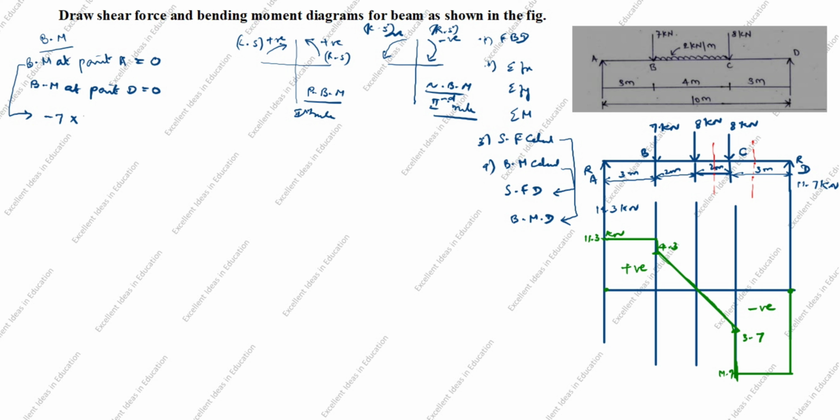3. Next, you see the arrow comes down only. From here to here you see clockwise. Clockwise is negative 8 into perpendicular distance is from here to here 5. Next, you see this arrow comes down. From here to here you see clockwise. Clockwise is negative -8 into perpendicular distance is 2 plus 2 plus 3 is 7.